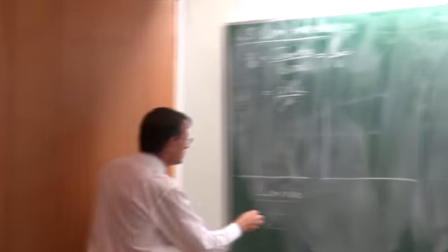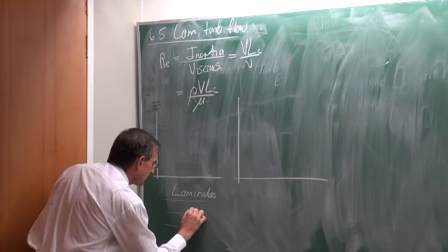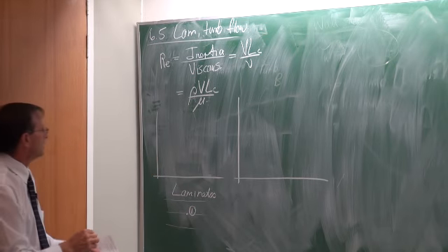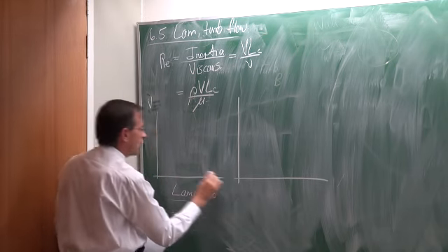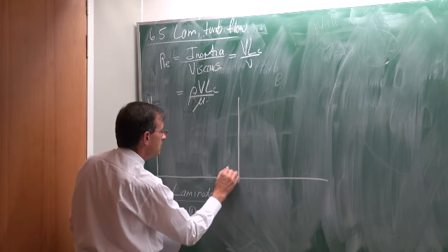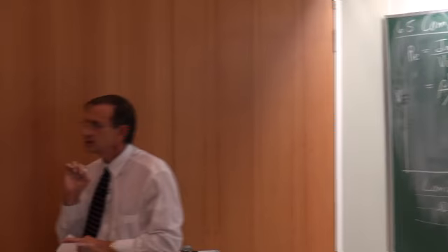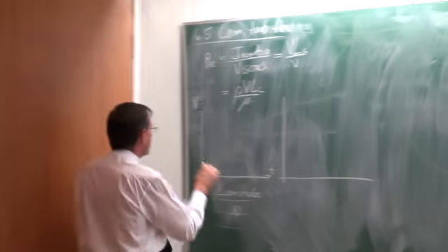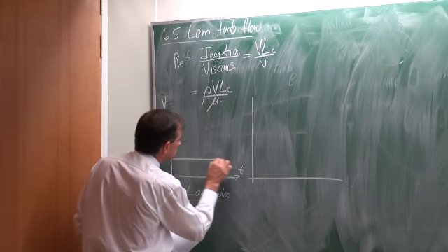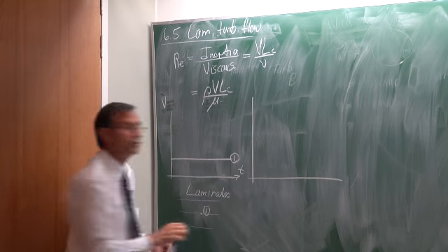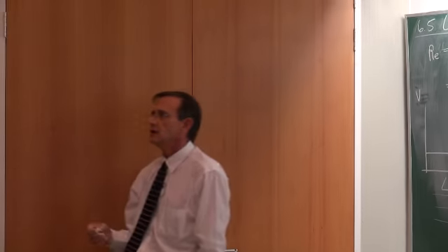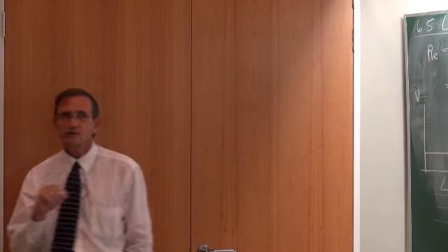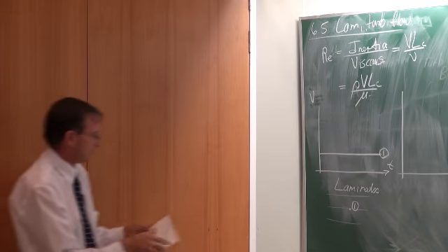If we would then take a measurement in that flow field, and we would measure the flow as a function of time, with some of the best instruments available on the market, then the velocity as a function of t would do something like that. It would be a constant. There will be no changes as a function of time. That is laminar flow.